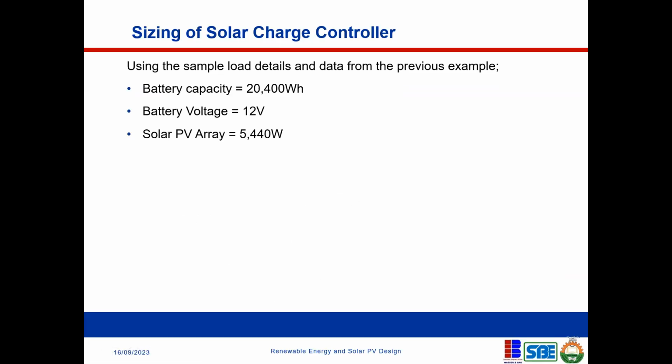Next is the charge controller. So we are going to size the charge controller. Now, let me also make a remark here that there are some hybrid inverters with inbuilt charge controllers. In fact, if you hear that an inverter is a hybrid inverter, it has a charge controller. That's what that simply means.